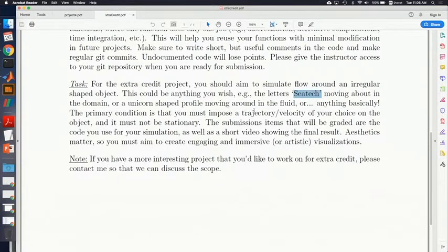So you don't just sit there and watch what happens when a flow comes by. There's no constant flow. Basically, think of what happens if we have the water testing tank outside, and you drag around an irregular shaped object. So what would the flow look like? So that's the idea. You take your object and you move it around, and then compute the flow. And again, with using penalty, you can do this very easily because U solid just becomes what you want to impose.